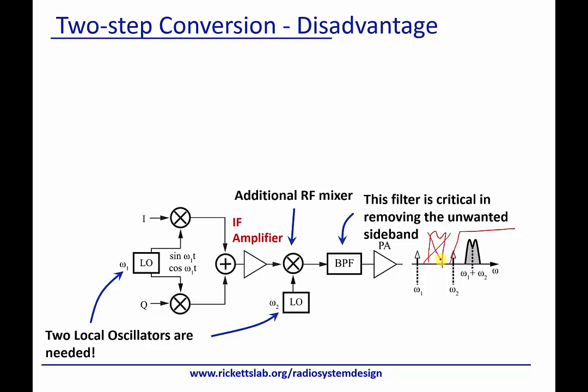A lot of cell phones now use surface acoustic wave filters, SAW. What they do is they basically take an electrical signal and launch it on a piezoelectric substrate in a way that it only transmits a very narrow band of frequencies. The reason we do this is that these filters have extremely low insertion loss and extremely sharp filtering, and so it's worth it to go into a specific technology just for these specialized filters.